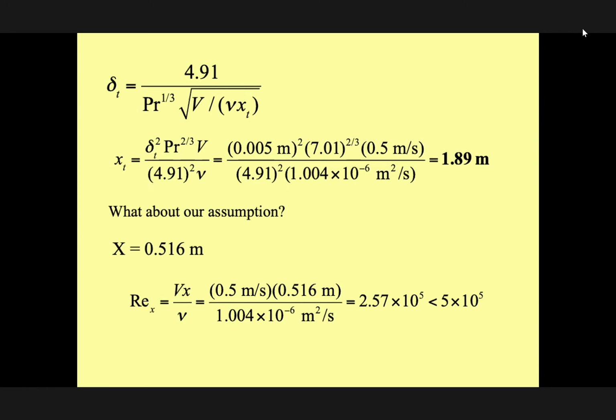You're right. You're talking about flow over a plate. And as we mentioned before, you're right, madam, if the Reynolds number is less than 500,000, the flow is laminar. If it's more than 500,000, it becomes transition and turbulent. Therefore, we are talking about flow over a flat plate. Here it is laminar because the Reynolds number is less than 500,000. Therefore, 2000 is only for flow inside the pipe. But we are talking about the flat plate.